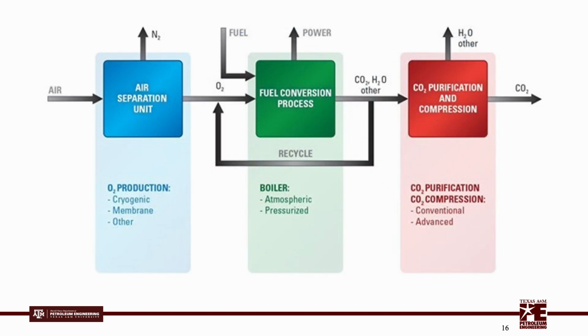Today's state-of-the-art oxy-combustion systems would use a cryogenic process to supply oxygen, atmospheric pressure combustion for fuel conversion in a conventional supercritical pulverized coal boiler, substantial flue gas recycle, and conventional pollution control technologies.